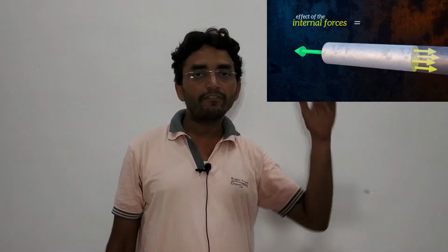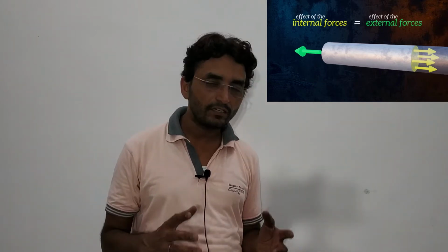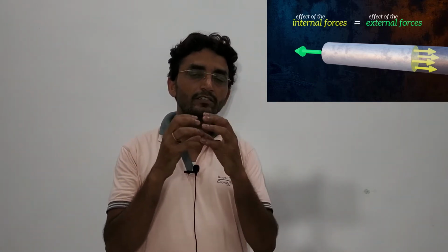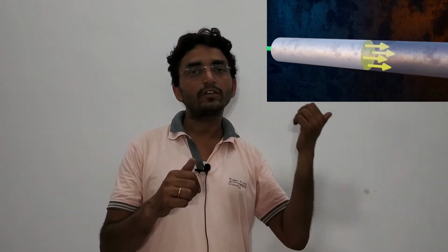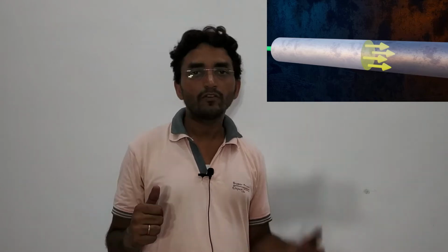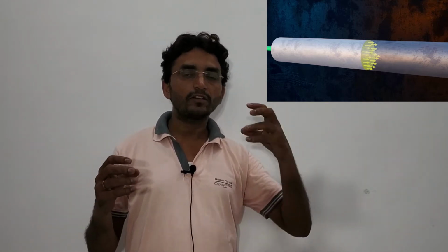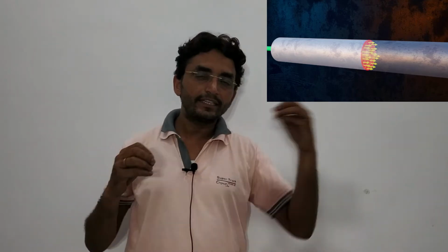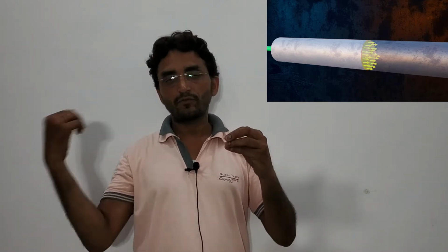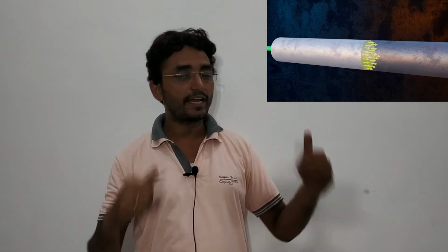They try to restore this deformation. We can see in the picture, if I cut this bar, some kind of internal resistance force is acting in the opposite direction of the external load which is acting on one end of the circular bar. If we cut the other side, we can easily see that some internal resistance forces are acting on this side against the external force on this end.